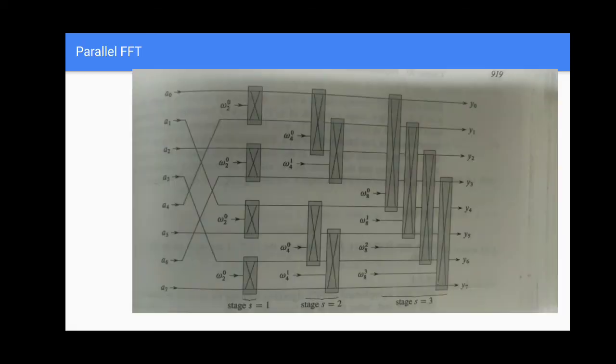Now the same thing which we have discussed in the iterative algorithm can be implemented as a parallel FFT circuit. Basically what we do is, the coefficients are arranged by this particular circuitry in the required manner, and then the omega values get computed and stored in the butterfly operations, and they are input like this, and hence the output vector y will be the discrete Fourier transform of the input vector a, which is connected in this particular fashion. The hardware circuitry is for an 8 coefficient vector.